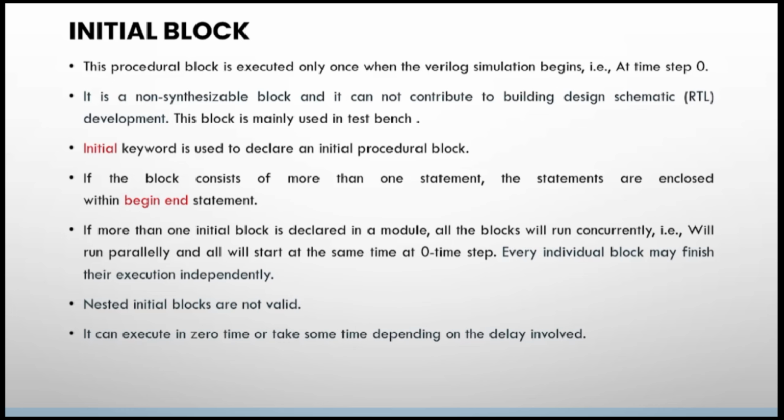Also, this initial block is a non-synthesizable block. That means it can't be used for RTL, it can't be converted into hardware. That is why mostly we'll use this initial block in test bench. When we are using this initial procedural block, we'll be using the keyword called initial. And in initial, if your code consists of more than one statement, then you should use the keywords begin and end. So within begin and end, you should be writing your entire code in the initial block.